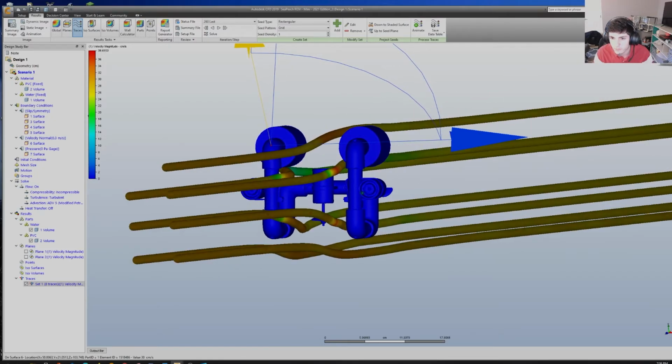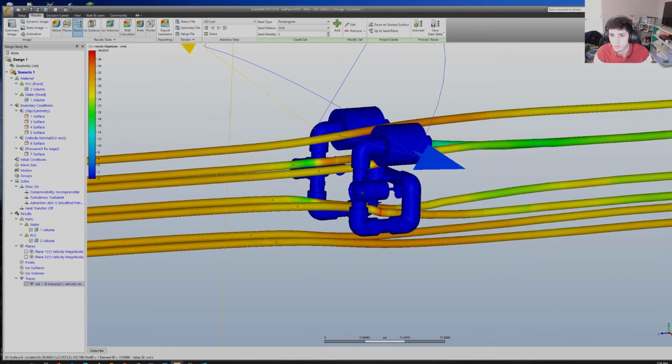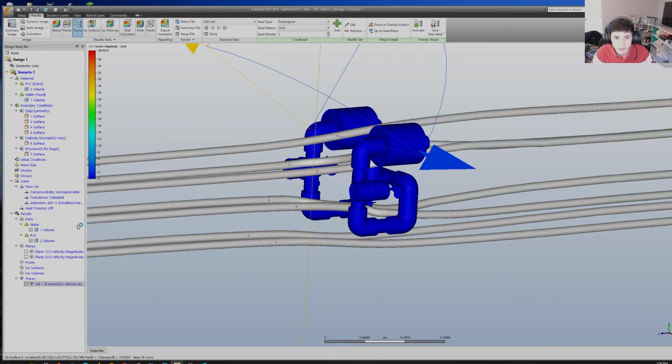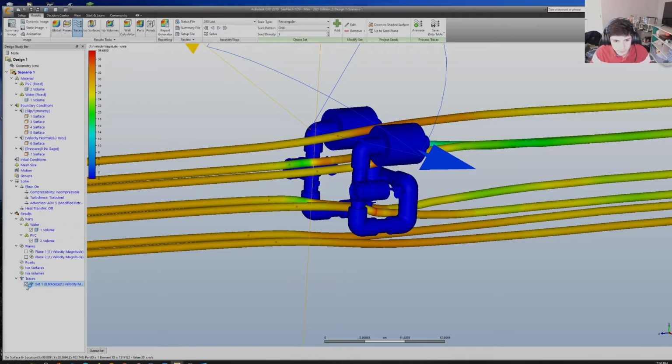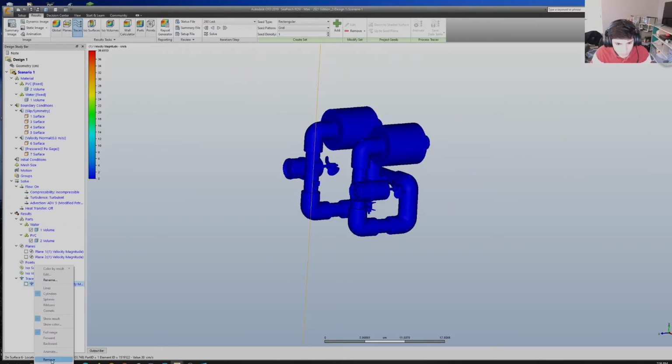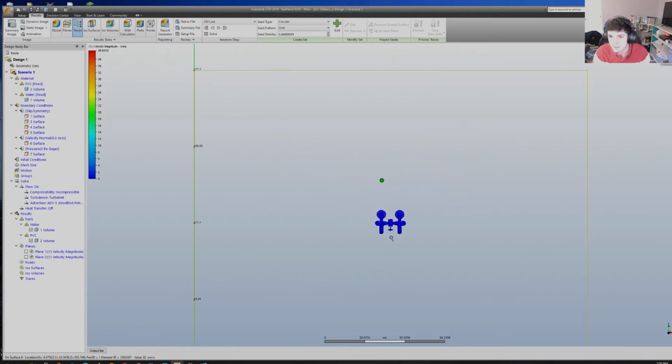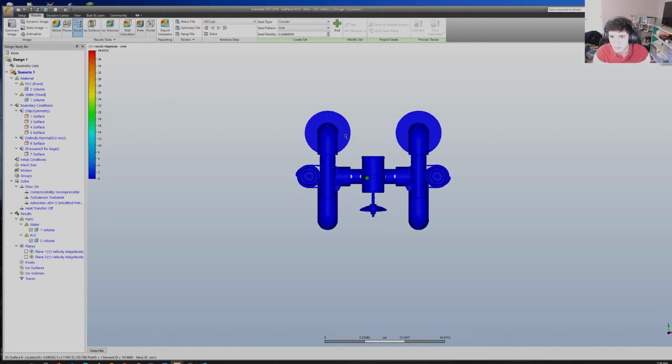That's just a rough idea of how it's flowing over in these specific areas, but we can modify this. So add, and if you don't want this to be a rectangular shape, let's say a circular shape, and you want more of the traces, you can decrease the seed density. So click there, click add.